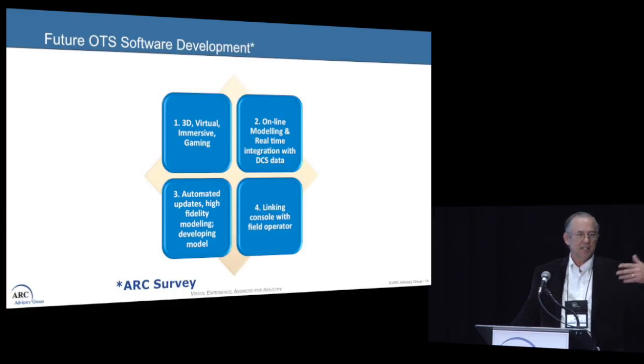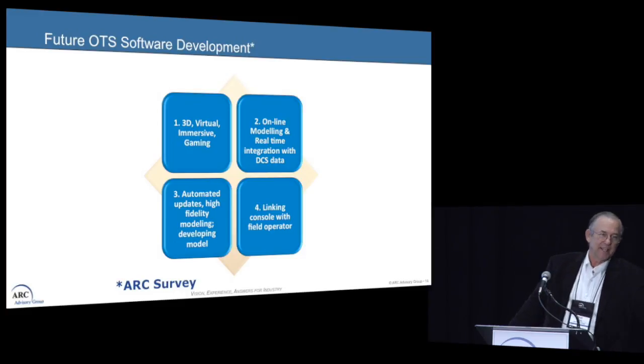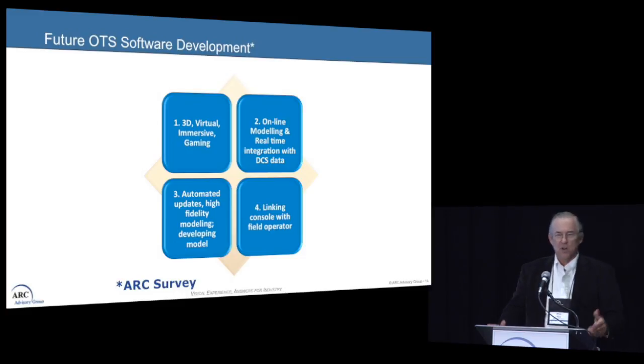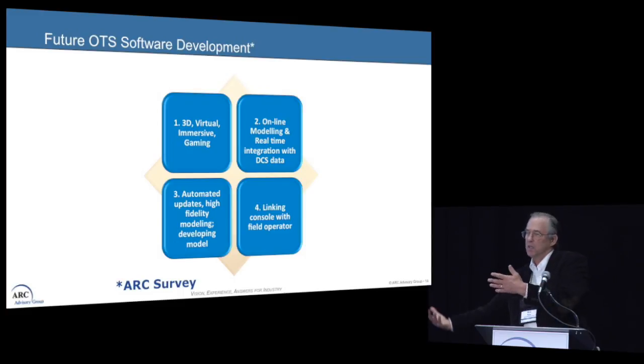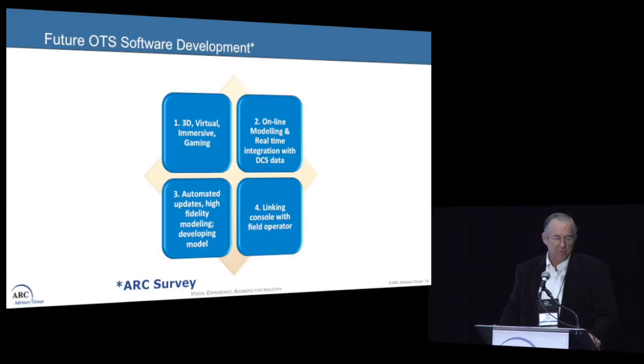And they change constantly. You have to go to the real control system and take that software and bring it out here. Now, almost all the DCS vendors can run that real software, the exact same displays, the exact same controls and alarms, and run that in a virtual machine and connect that to a training simulator of some type. And that's really important.